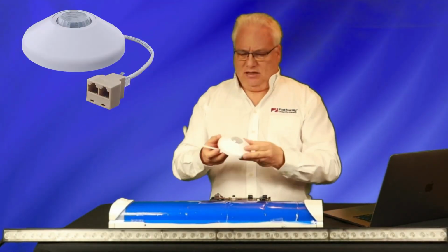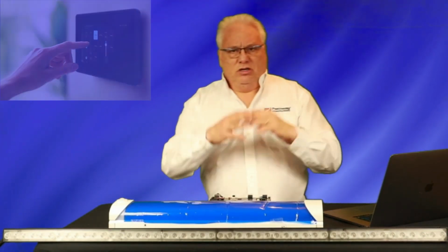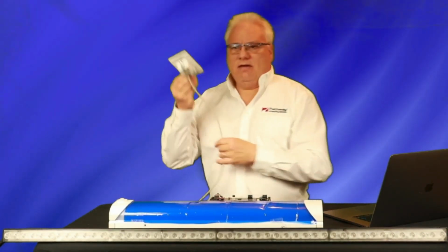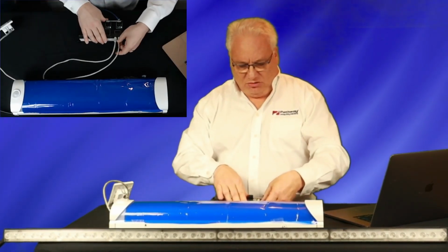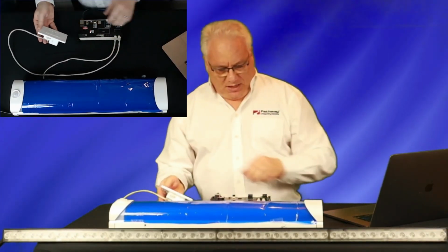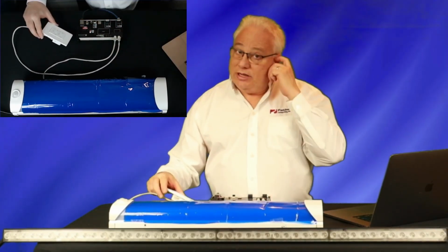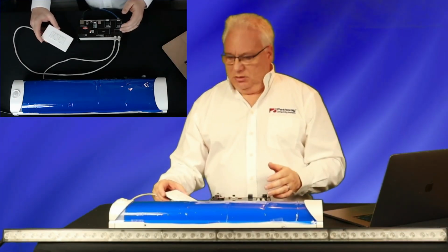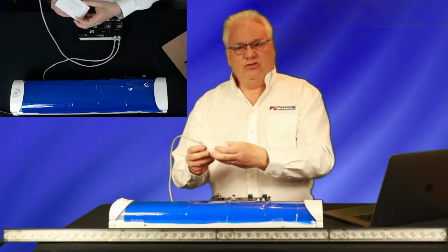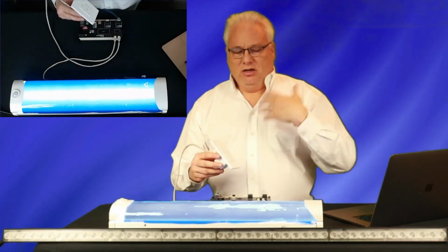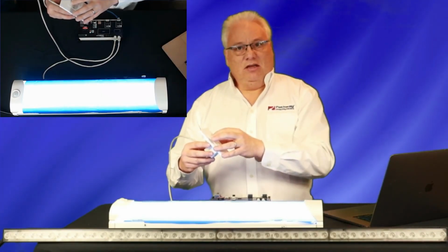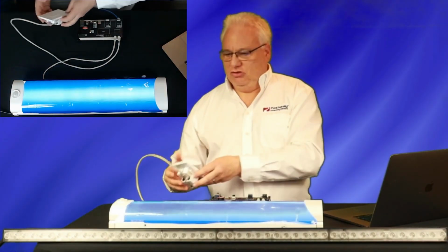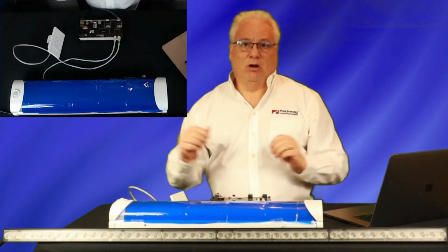Now, I can control this with any nLight device like an NCM or NTS, but I have an nPod MA here. This one is a 2P, so I will plug that into the other side of my nLight port, and the nLight port is supplying 40 milliamps of power. And after it's done the negotiation, I can just press the on button here and we get intensity on channel 1. This is nothing new. What will be exciting is when we actually use the second switch to do something dynamic on our mark fixture.